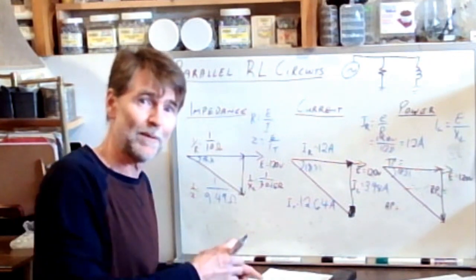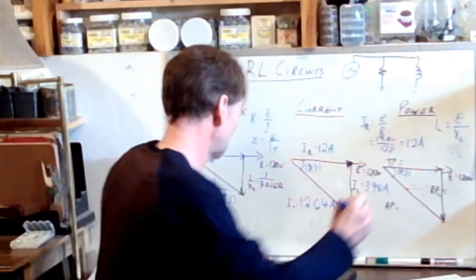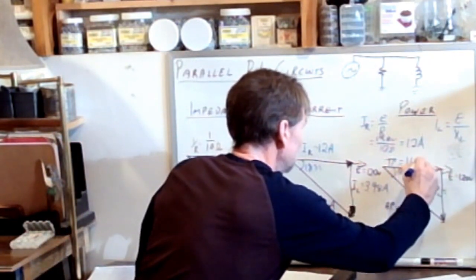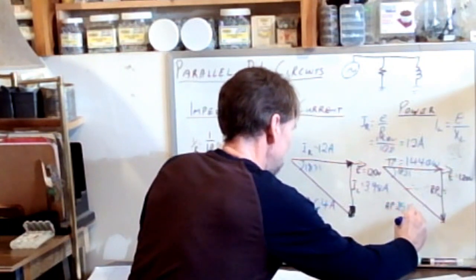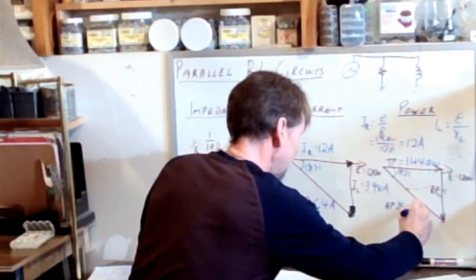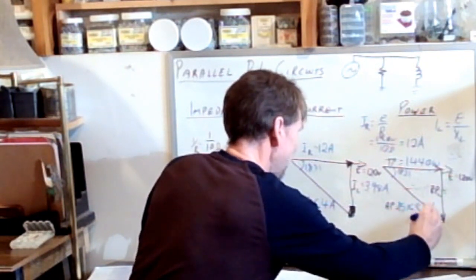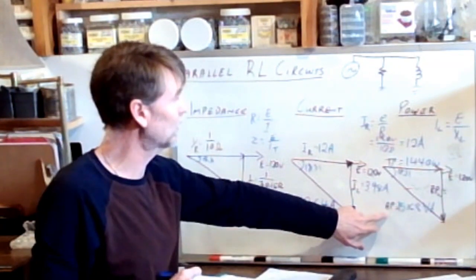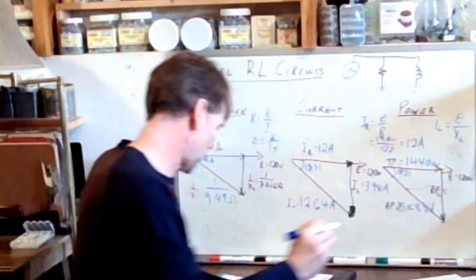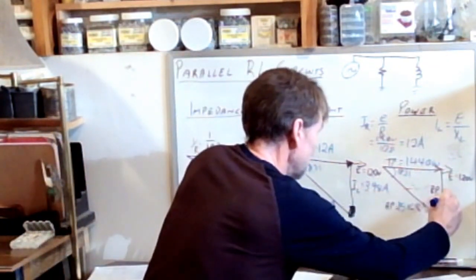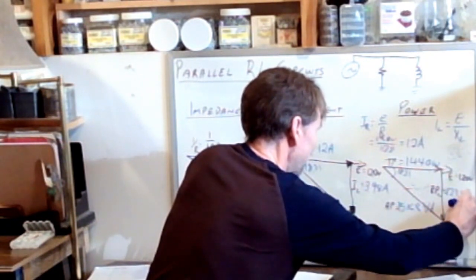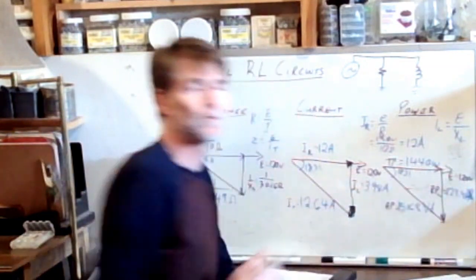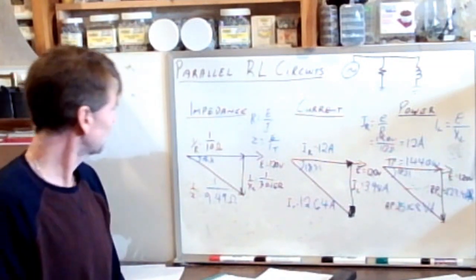Hit pause. I'm going to fill in the numbers. 1440 watts goes there. 1516.8 volt amps is the apparent power. And the reactive power is 123.9 VARs.